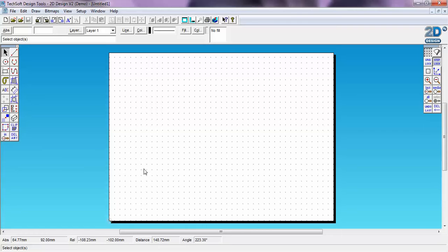So the next tool, which you may be familiar with, is the Line tool. The purpose pretty much fits the name. You use it to draw lines. Now, as you can see, the background is a grid. Each one of those individual squares is 1 cm by 1 cm, and so this can help you with measurements. When using the tool, you simply select, hold down your left click, and then drag to form the line, and then release it.